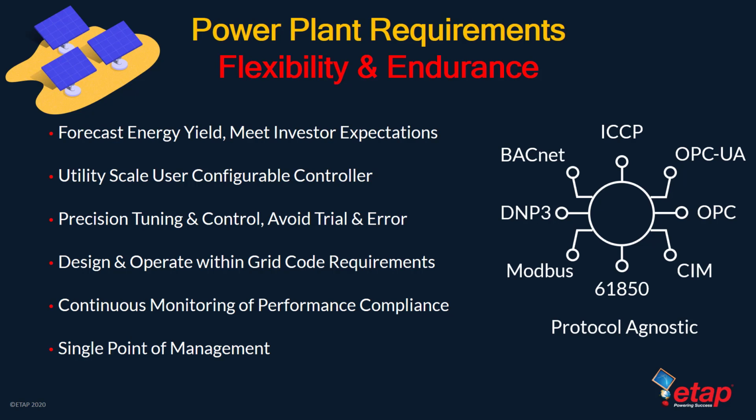The typical procedure for predicting the energy yield of a PV plant is through time step simulation software that runs typically at hourly or sub-hourly steps. And that may include estimated losses, site conditions, and historical irradiance. These are good for estimation, but where they fail is to include detailed AC and DC losses, auxiliary power or balance of plant, grid availability, grid compliance losses, as well as the power plant controller performance.